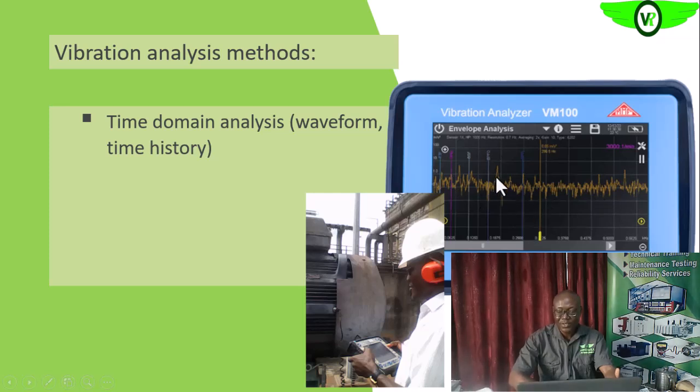Like we said earlier, if these intervals are equal to the RPM, it could be an impacting event that corresponds to 1 times RPM, which could probably be a result of imbalance, or any other 1 times RPM event. Are we getting it? Those are the few things you can glean from the vibration data.